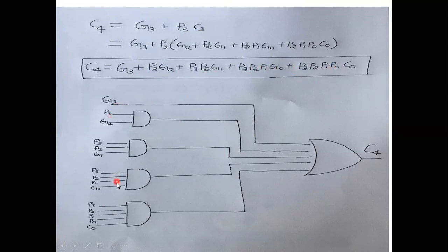Here also, after writing the logic circuit, you can note that all my G3, P3, G2, P2 functions will be available after one gate delay, one more gate delay for the AND gate outputs, and one more gate delay for output of OR gate. Finally, C4 also will be produced after 3 gate delay.